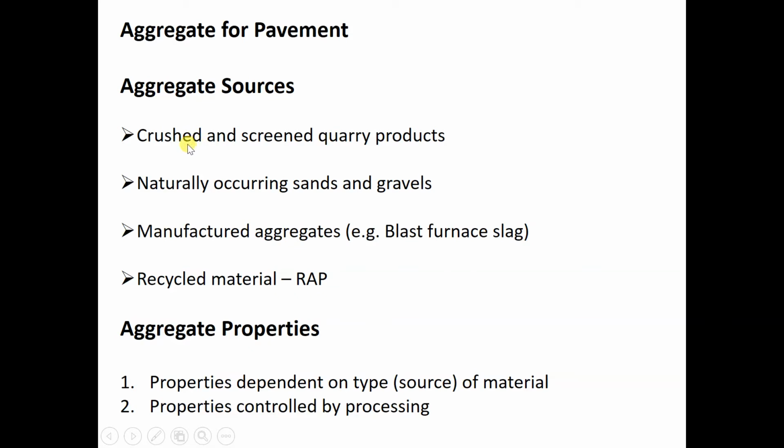They get a lot of big chunks of rock on site, so they need to use dynamite to blow it up, and then they bring the big chunks of rock to the crusher, and with successive crushing you produce different sizes of aggregates.